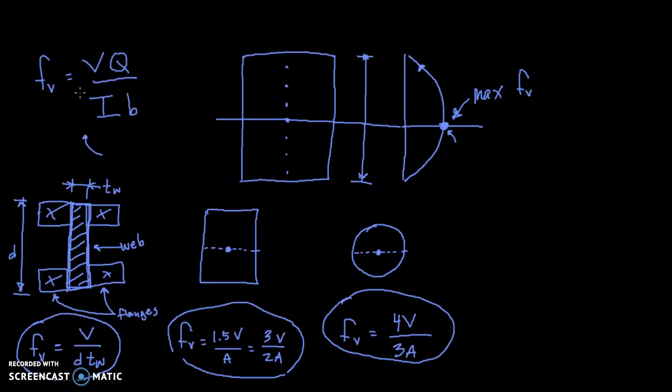If so, we probably would need to go back to this original formula up here and figure out what the stress is. But if we have one of these 3 types of cross sections, a wide flange, a rectangle, or a circle, which is going to be all, if not most all, of the problems we deal with, then we'll be using one of these 3 formulas.